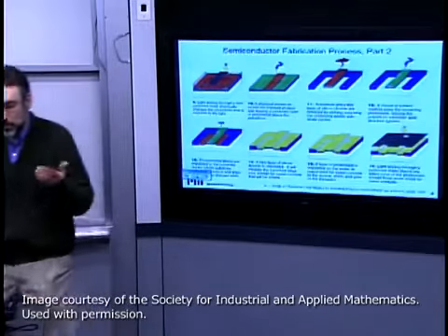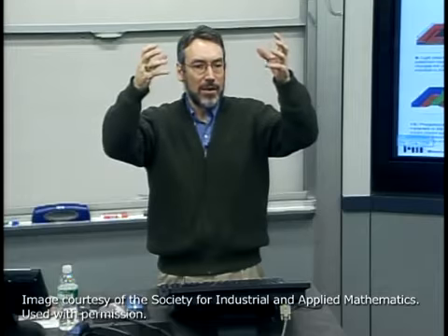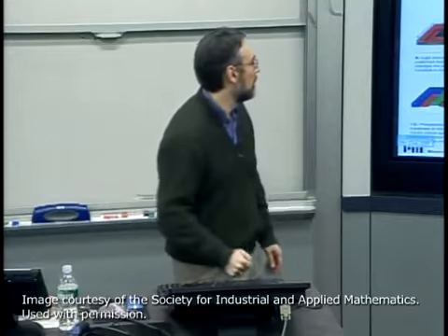In this case, we typically use a chemical vapor deposition process, again in vacuum equipment, but we decompose silicon dioxide carrying molecules in a gas plasma. So there'll be a more complex molecule typically coming in, and we decompose that, and basically it snows on the surface of the wafer and builds up a silicon dioxide layer.